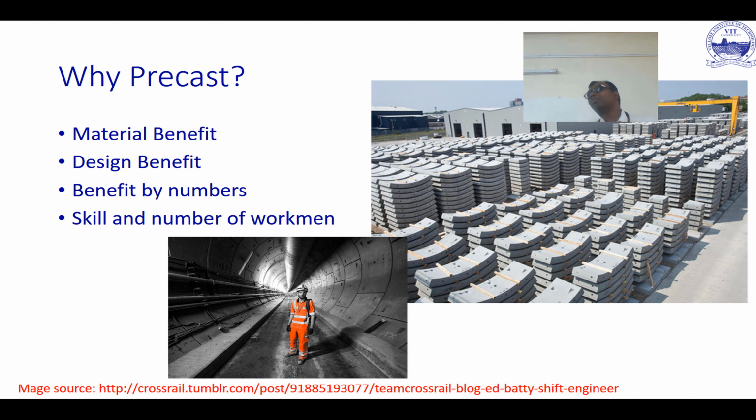So these are the benefits of precasting. You save a lot on the material. Okay. The reason is because it's a controlled environment, you don't have to give a higher target strength. Typically what you do, you tend to give a very high target mean strength so that the 5% or whatever is the limit state which you are looking at is definitely satisfied. So this is one of the first and most important things about precast concrete.